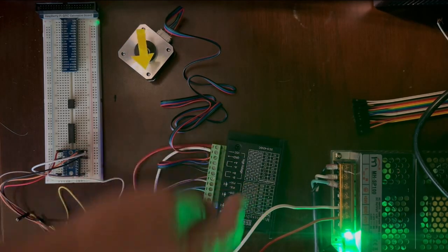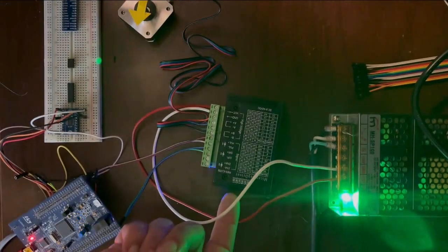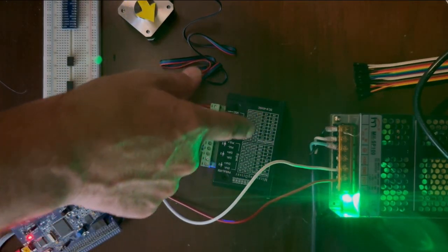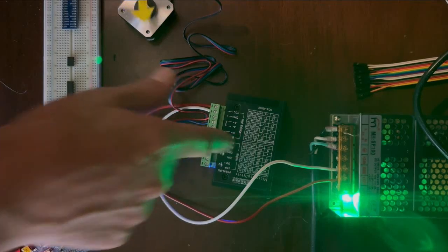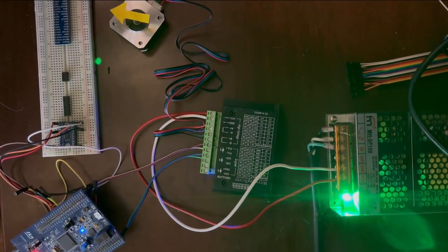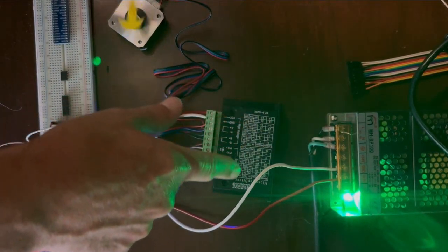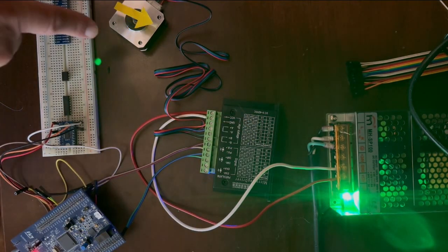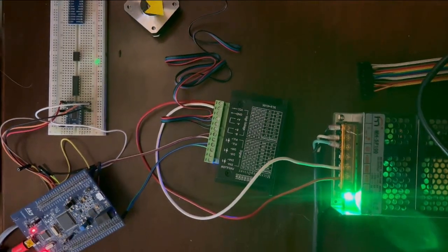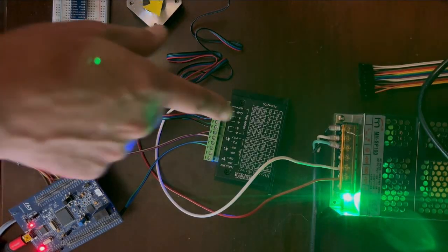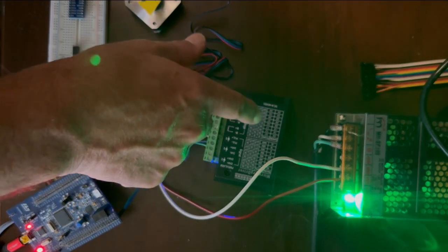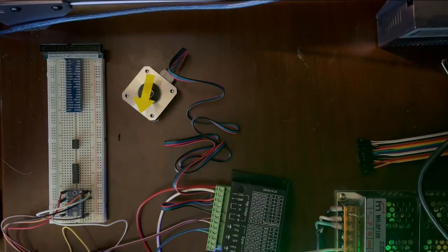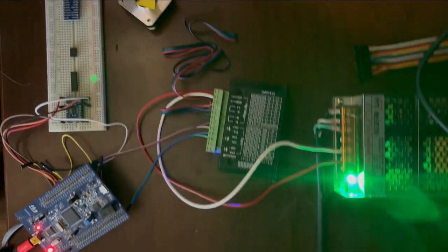There are some dip switches on the side here that you can't really see, but these configure your stepper motor. So I have it configured a certain way. I think I have it configured for 1600 pulses per revolution. Then over here you can set the drive current, which I have set pretty low because we're not really moving any loads. So I just wanted to keep it pretty basic. Then of course the stepper motor over here. So it's a pretty simple hardware setup.